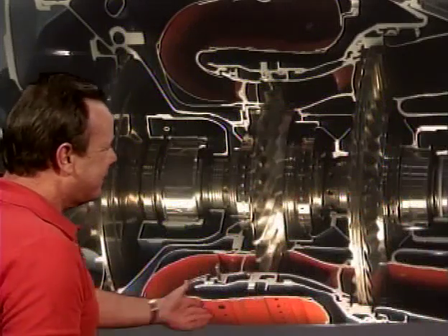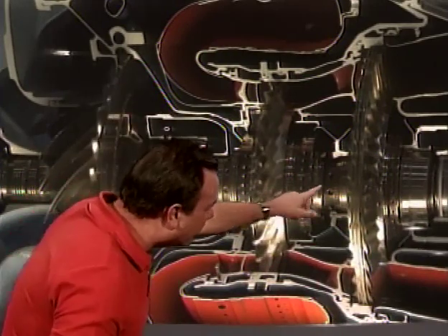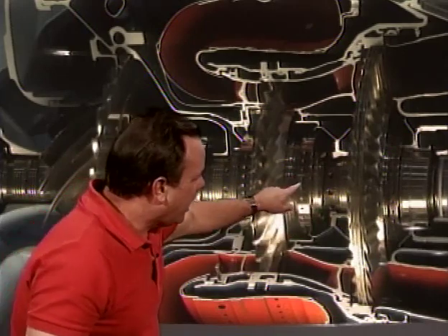When mechanics have an engine all apart and they're looking at it, they like to talk to each other, and very often you'll see some guy get a pencil out and he wants to mark what he's talking about. Well, the FAA wants you to know that turbine engine components are exposed to very high temperatures, and creating a little pencil mark may create a weakness later on that could cause that part to fail.